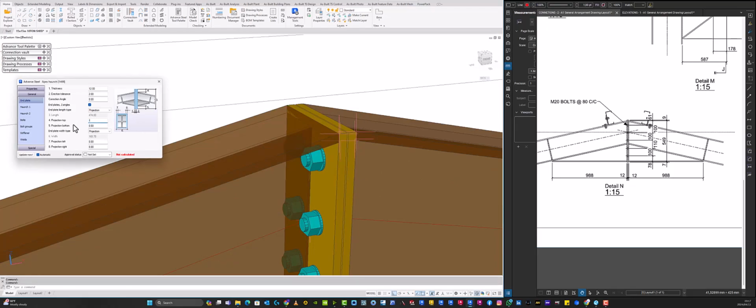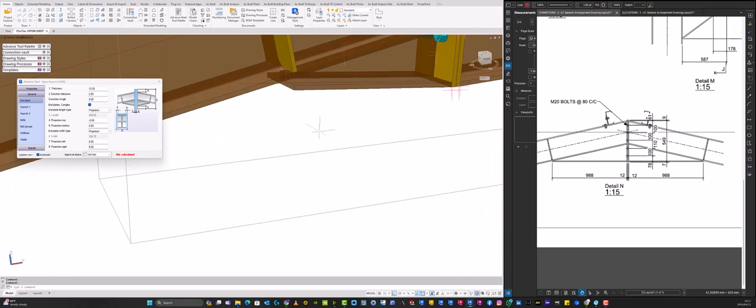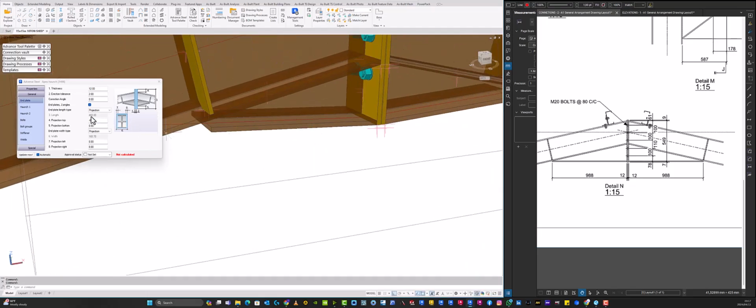So at the top, if we just zoom in there, from there at the top, if you go -6, there you go, we've got that welding bed there between the top corner of the flange and the plate. We've got 6 millimeters. And then let's check at the bottom as well. At the bottom, if we add and say -6, there we go.